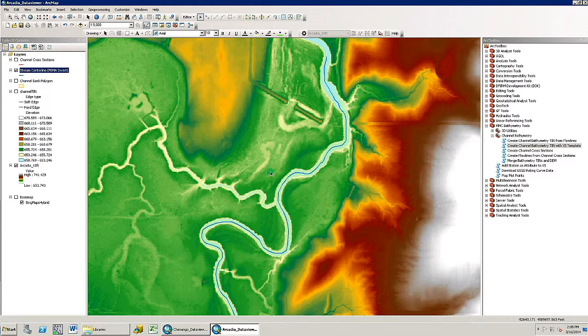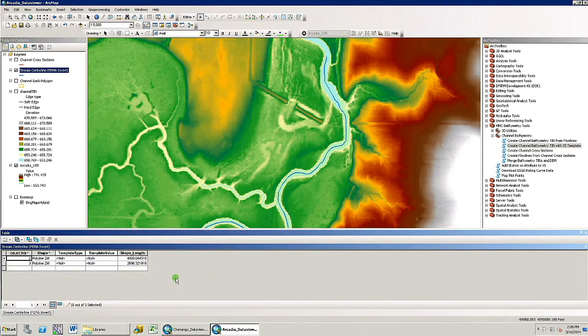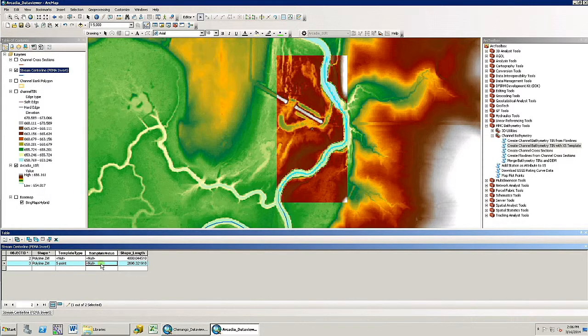To define a template separately for multiple reaches, the tool will work off specific fields and attributes. So these fields were automatically added when I ran the Create Channel Cross-Section tool in Step 1. I'll attribute the downstream reach as a 5-point cross-section, and define the percent of top width for the bottom width. We'll go with 50%. Now I'll attribute the upstream reach as a V-shape. I do not need a template value for this type, so this one remains null.